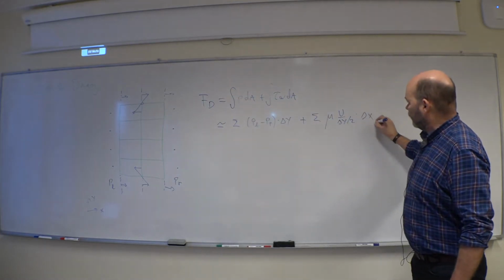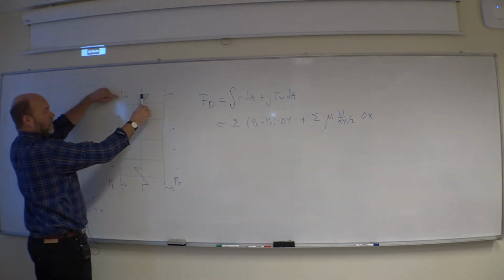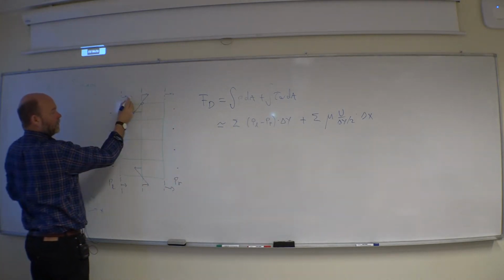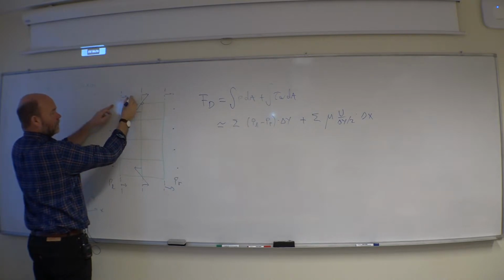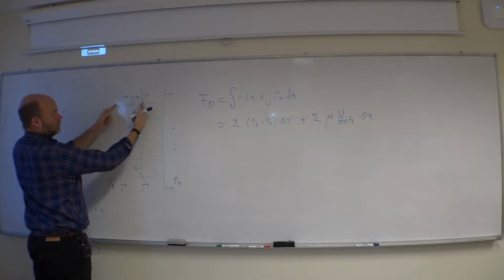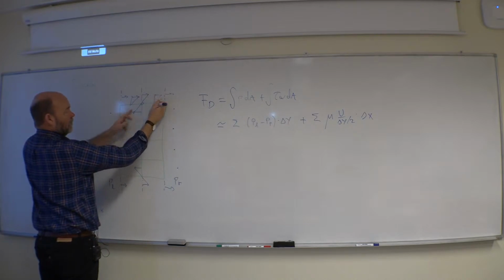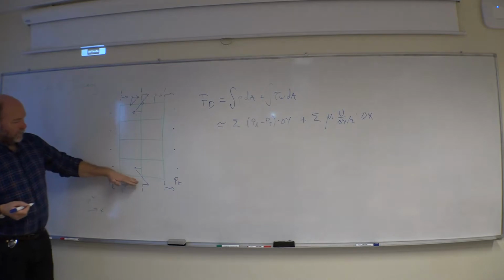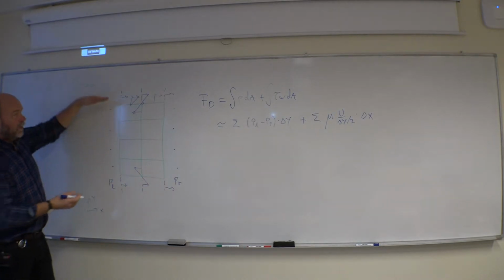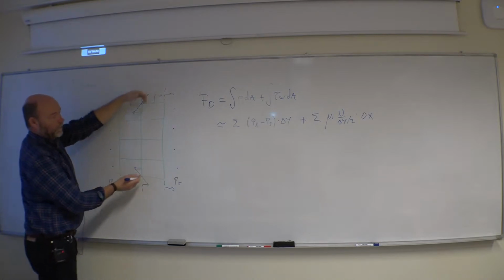Of course, here you might want to do an interpolation, finding the velocity at this point, and you have 0 down here, and then it will act on just this delta x, and the same average here, to get it more precise. And then you of course do the same down here. So the friction forces acting on the top and the bottom.